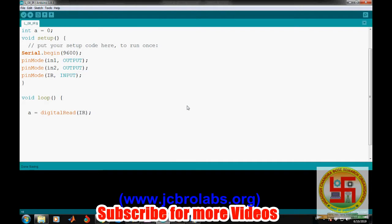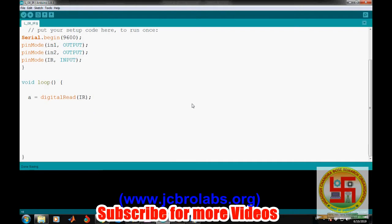It will read the status, and if it is 1, A will go to 1, otherwise 0. So if there is something in front of it, we should turn off the motor, and if the IR sensor is not giving any 1, the motor should turn on. Okay, so we use an if else statement.